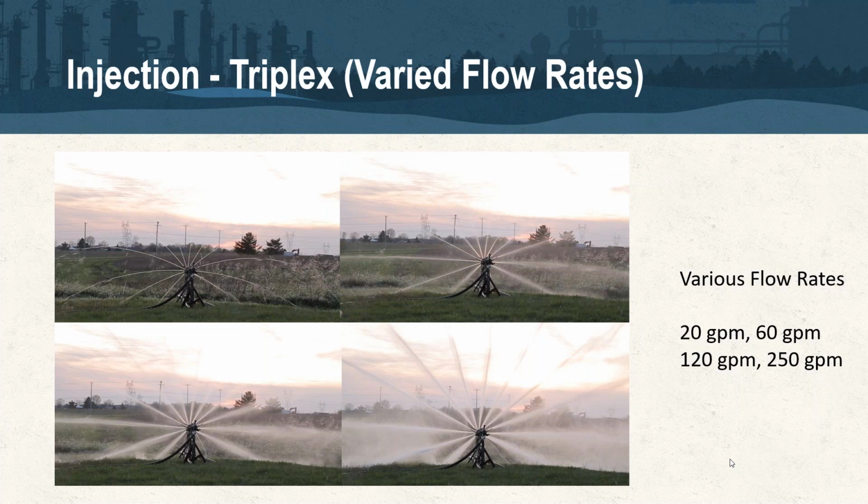But it's also important because we need these flow rates to achieve distribution. At some sites, we're not looking for the low end. We can get 20, 30 feet of ROI. At some sites, we've had as much influence as 100, 120 feet away. But our typical designs are going to be somewhere between 40 and 60 feet between the injection boreholes. So we need that power behind us to continue to propagate the injection material into those features or fractures that we're working with.